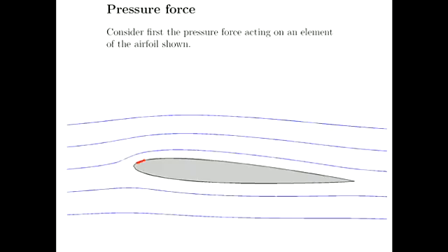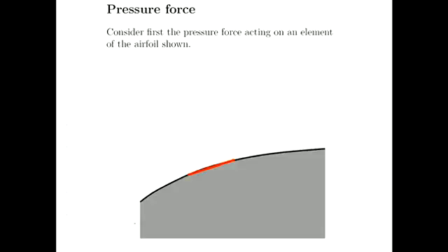So let's have a look at that a little bit closer. If I consider some element of that aerofoil, a tiny element at the front of the aerofoil, we can write out simple expressions for that lift and drag component, all right? So I'm going to consider this element that's got an elemental area dA, and a pressure acting normal to that element as shown on this diagram.